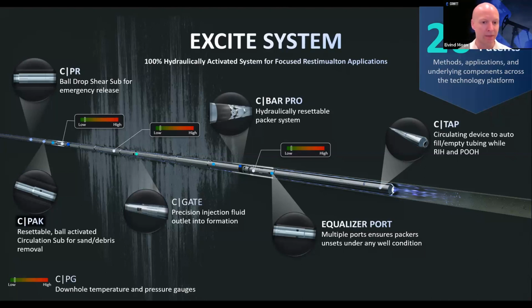And in this case, we have a lot of flexibility in how to design this and how to space it out. Depending on your wellbore configuration, we can treat your original frac stage, or we can even go down in some instances to the individual perforation cluster level. So we can space packers out basically however we want, and we can divide a whole lateral up into 20, 30, 40, and then 60, 70 treatments, depending on whatever makes sense.